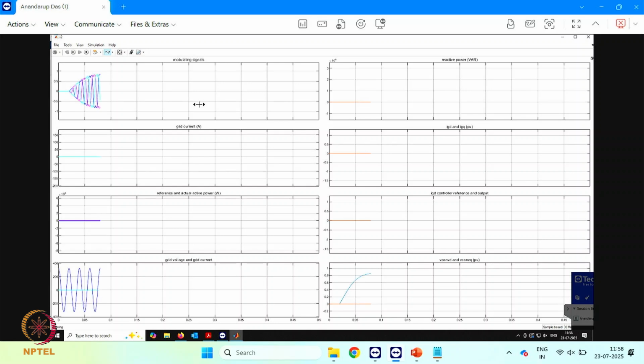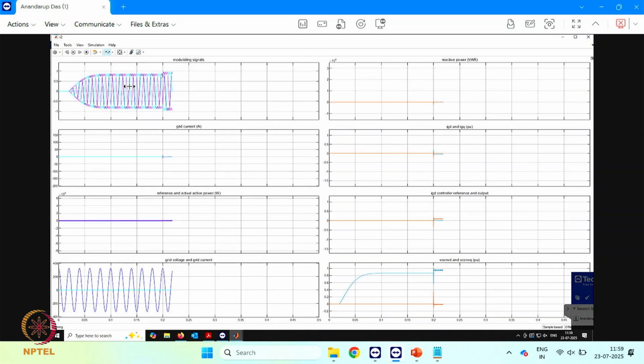It starts again with the same strategy. Here you can see initially the converter is booting, kind of coming up. We can say in computer language booting up, just for fun. Not exactly booting, but in the initial part the breaker is open, and now here I have turned on the breaker. At t equal to 0.2 seconds the breaker is on, and there is an inrush. Now let us continue.